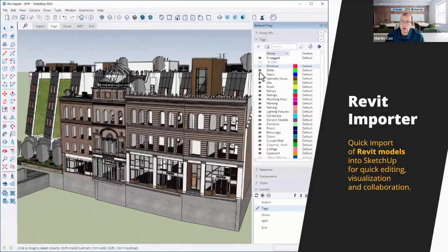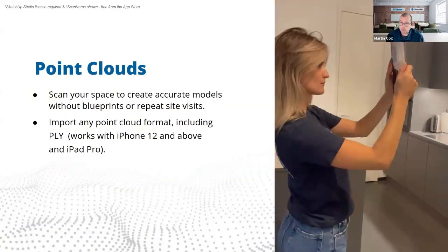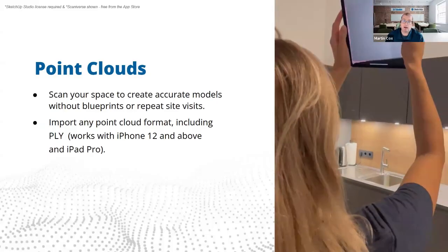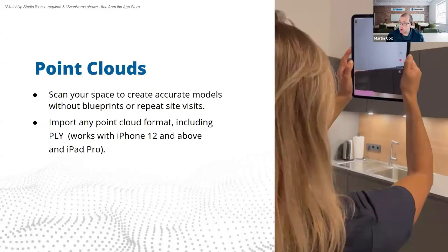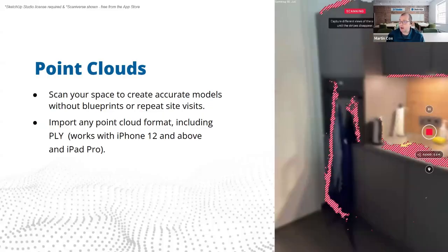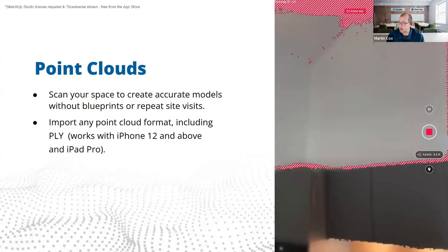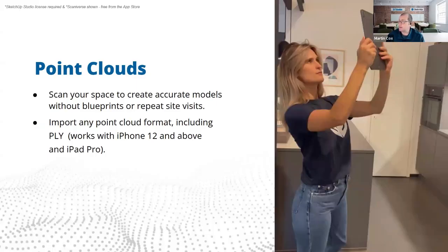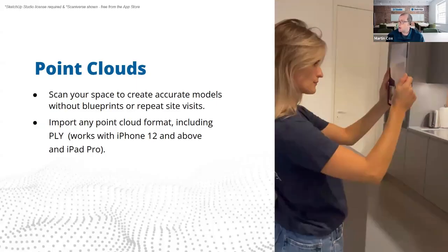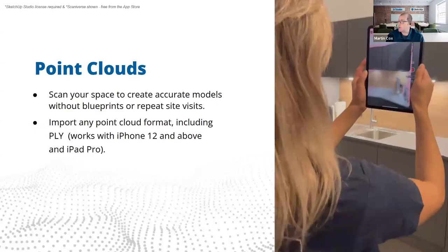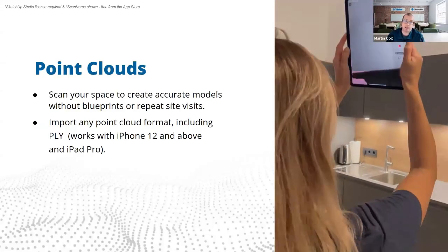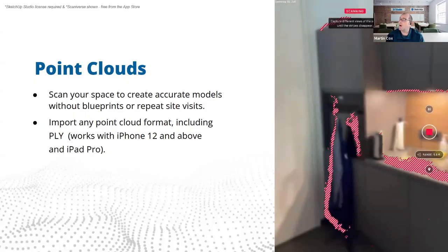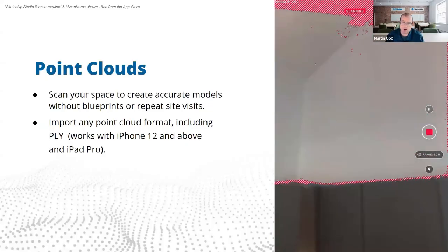Also point clouds. Point clouds are an amazing way to get working with bringing in your model. You can scan your space to get those models, and you can work with that point cloud directly inside SketchUp. In this example that we're showing here, we're scanning using an iPad. iPads and iPhones have a built-in LiDAR scanner, and you can scan smaller spaces and smaller models using just the iPad.